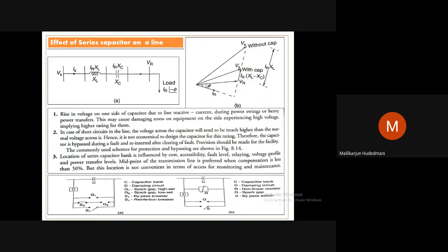Let us view the receiving end voltage VR, and from the receiving end voltage we will construct the value of VS, the profile of the sending end, in reverse. Let's say the vector shown here is VR, the receiving end vector, and there is a draw of current which is inductive, IR lagging by phi.